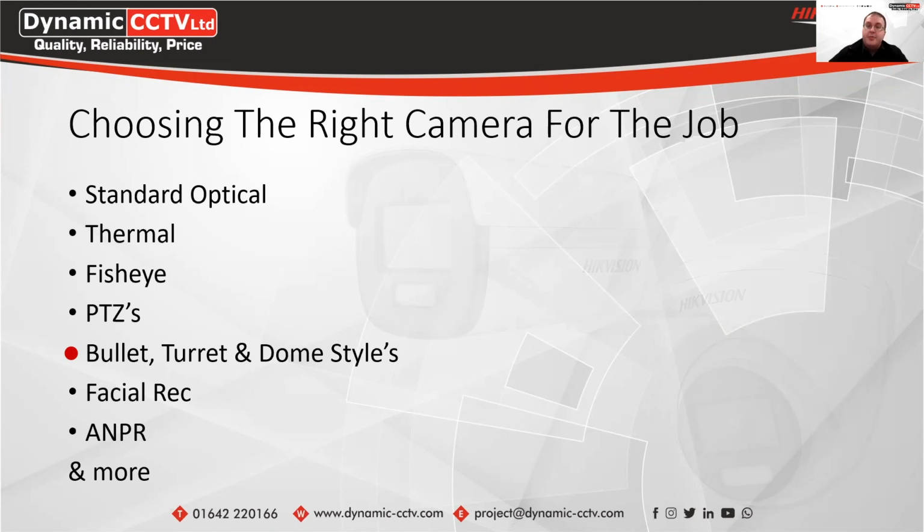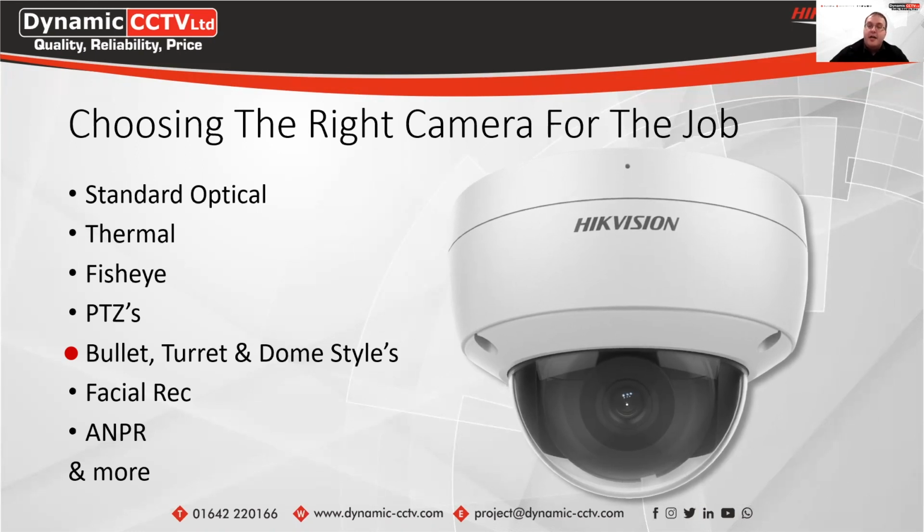Generally what you'll see with a dome camera is if it's mounted outside, muck will stick to the actual dome lid, and that can have an effect on the actual image that you're seeing, and also can reflect the IR LEDs as well, so it can reduce the overall quality, especially at night. So we do now recommend and see a lot more bullets and turrets being installed outside as well.